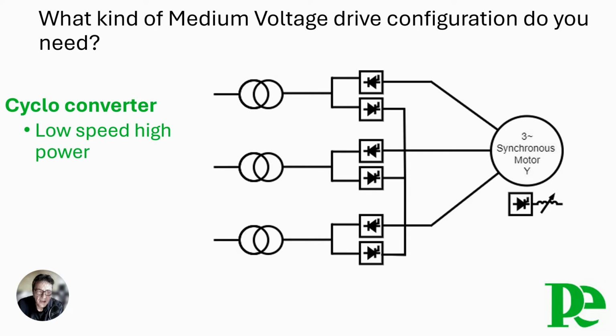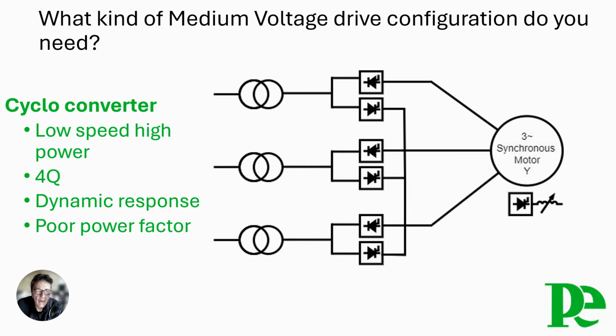This converter offers high efficiency and bidirectional flow with low space requirements and great dynamic response. This all within a simple and robust structure for power ratings of 3 up to 50 megawatt. However, the operational speed is limited to 44% of the line frequency and the total power factor is rather poor, thereby often imposing the installation of filter circuits.